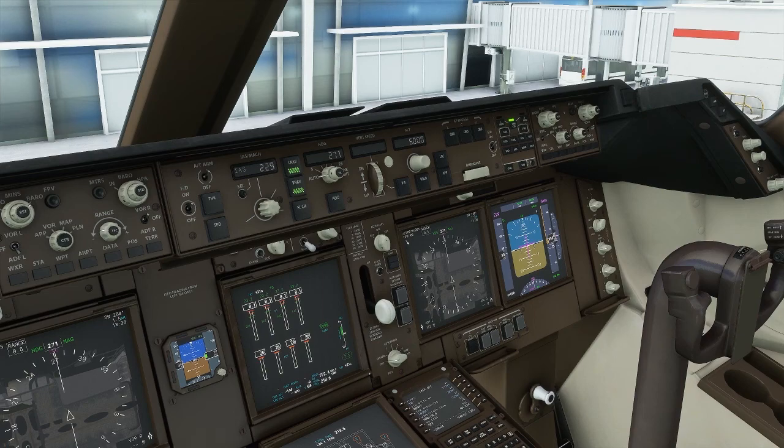Yeah, that's the autopilot. That's the altitude window. So we set 6,000 feet. These are your autopilot buttons. Normally you would only have one selected unless you were doing an ILS approach, and then I think it was 1,500 feet or something. All three would engage. And that would be for auto landing if you're in poor visibility, stuff like that.